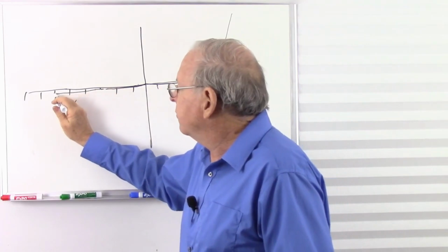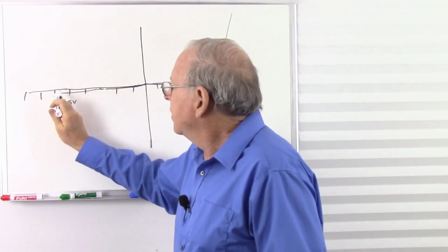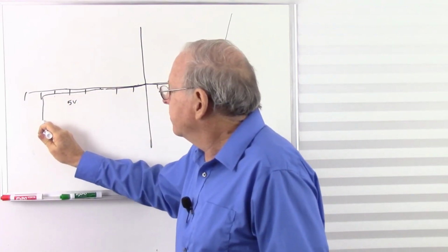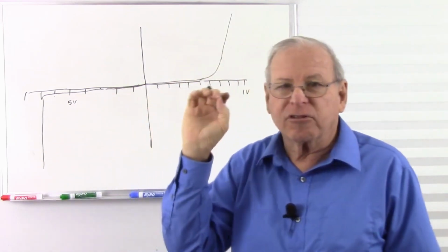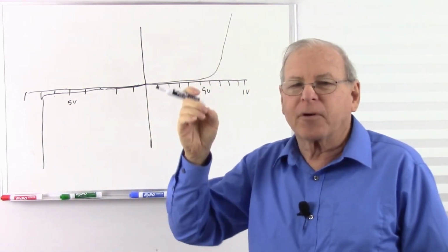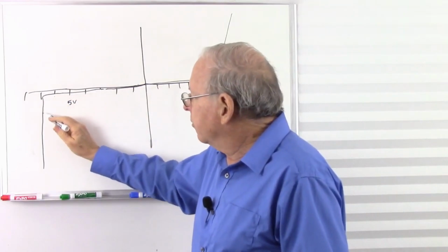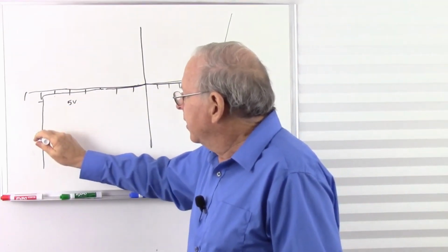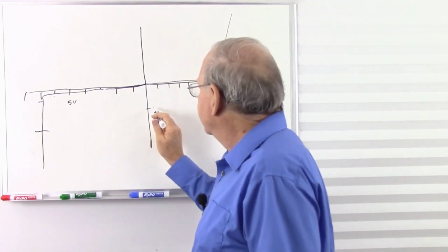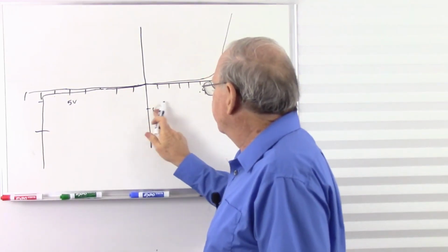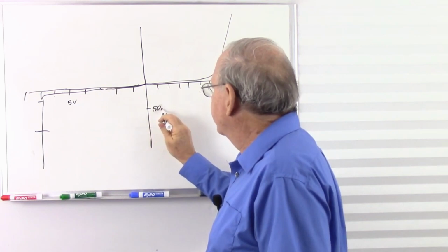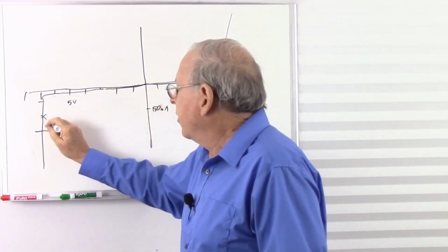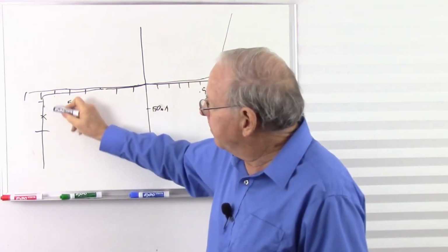We get up to around 7 volts. It's going to be a lot sharper. Very, very tight turn, and even higher voltages, it's almost like a crease. So it gets a sharp turn and goes much straighter up and down. But remember, it's designed to operate in this region where we get maybe 40 or 50, let's make it 50 like we had before, 50 milliamps. So we want to operate it right about at that current there, so we want to keep it right there.